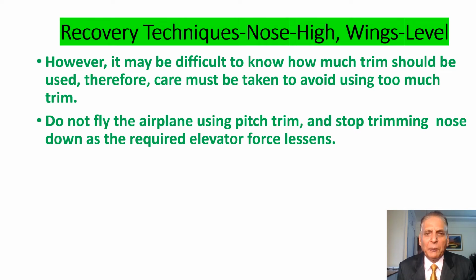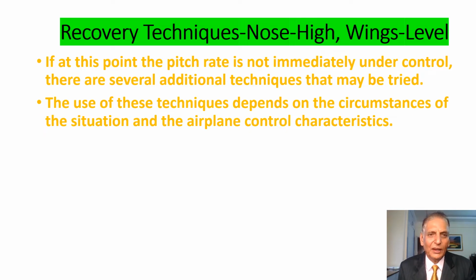Pilots should not fly the airplane using pitch trim and stop trimming nose down as the required elevator force lessens. If at this point the pitch rate is not immediately under control, there are several additional techniques that may be tried. The use of the techniques depends on the circumstances of the situation and the airplane control characteristics.